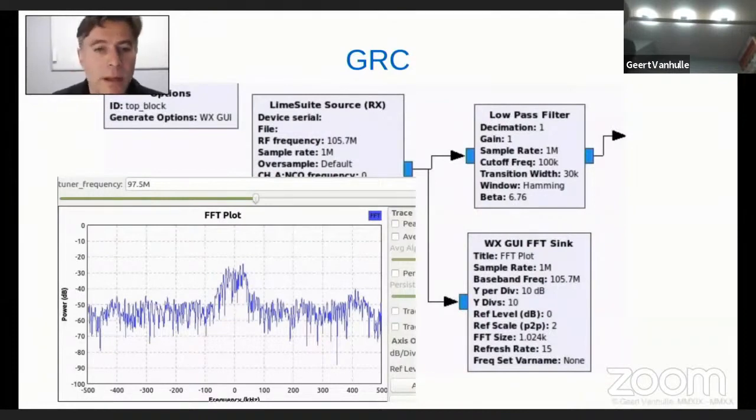And we can do this, and this is strange because normally in an analog situation we would need a bandpass filter to filter out this 200 kilohertz. Now we need a low-pass filter because, well, what is a low-pass filter? It's from 0 hertz up to a certain frequency. And now we have a low-pass filter that will filter frequencies out from 0 hertz up to 100 kilohertz.